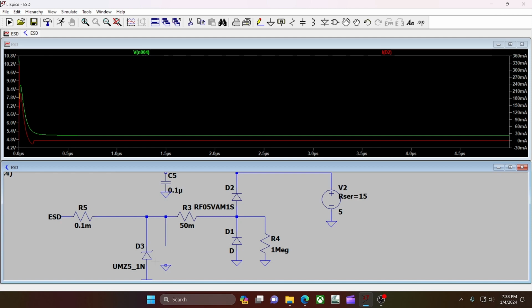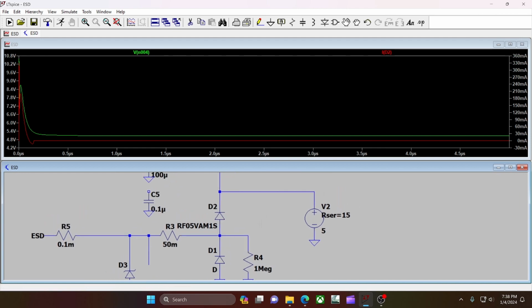So I wish these data sheets would go into that a little bit more. And for the 3.3 volt as well, for their clamping voltages. None of them said it's okay. So I looked at the clamping voltage and I said, it's higher than the max. So after exhaustive research, it's okay. Those TVS diodes can go above. You are above the limit for such a short period of time and you have these ESD diodes to protect you, you are okay. So go for it.